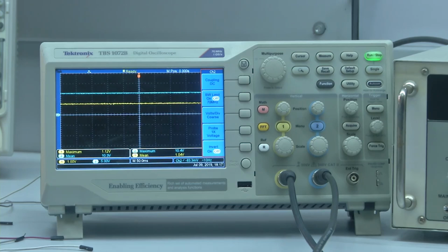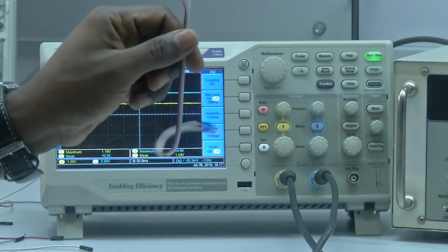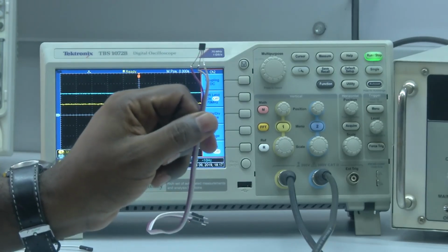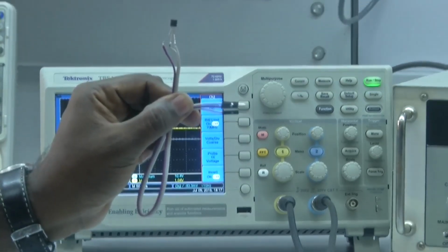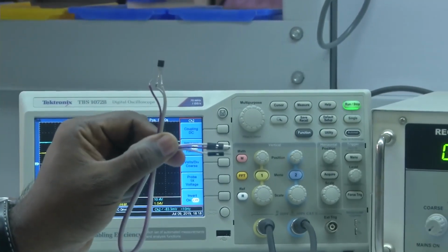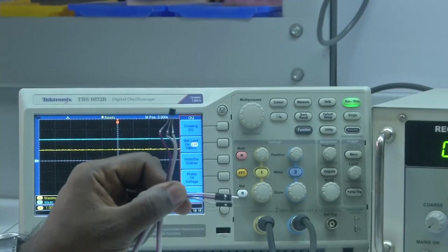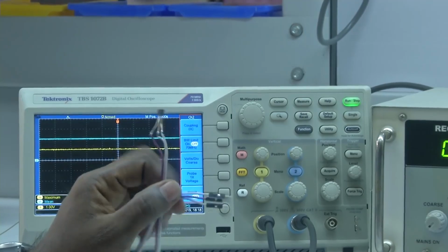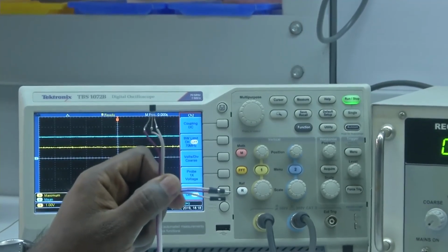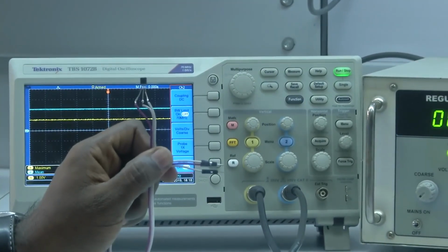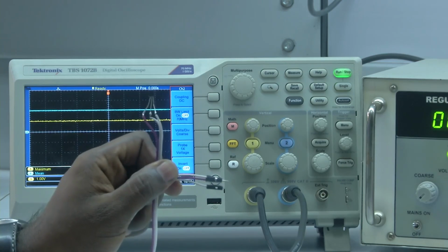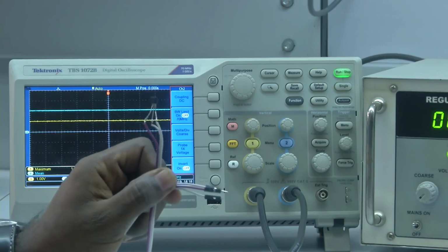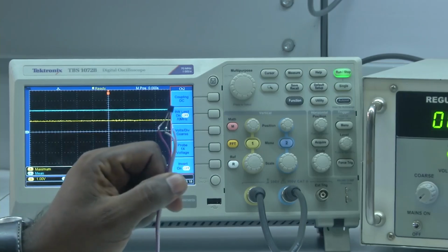Now what we do is that here we have the LM35 temperature sensor. We will connect the output of this LM35 temperature sensor to the board, and we will observe what output voltage we are getting from the complete system. In order to understand the temperature of any system, we can look at the output voltage. Since we do not have any heating source, we will use a soldering station which will always be heated to some particular temperature. By looking at the output voltage of the system, we will understand at what temperature that heating station is.